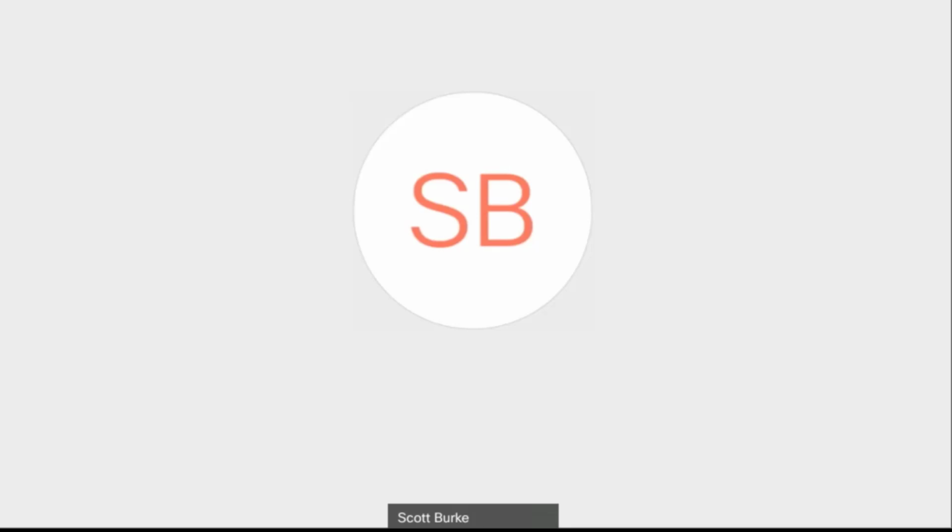Another question is a good one here. Can BIM 360 be used to share files to consultants who do not have a BIM 360 subscription? Well, a few days ago, the answer would be no, but that's actually now different. There is an option in BIM 360 Docs where you are allowed to share a link to a file with external people who do not have licenses. So this only allows them to download the file, not link directly into the system. But if you want to take a file and send it to someone via email, you can go into the system, pick a file, hit share, and use the option to share it with an outside person.